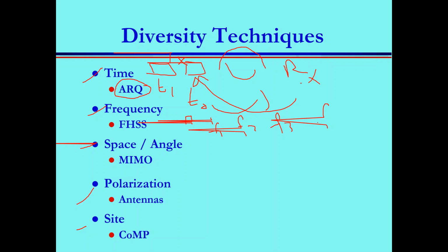When you keep jumping over all the frequencies, your performance will get averaged. Instead of being locked to one extremely deep interference channel, you get just 1% of the extremely bad channel, 1% from the good, 1% from the middle one. Then when you average, you get high quality.